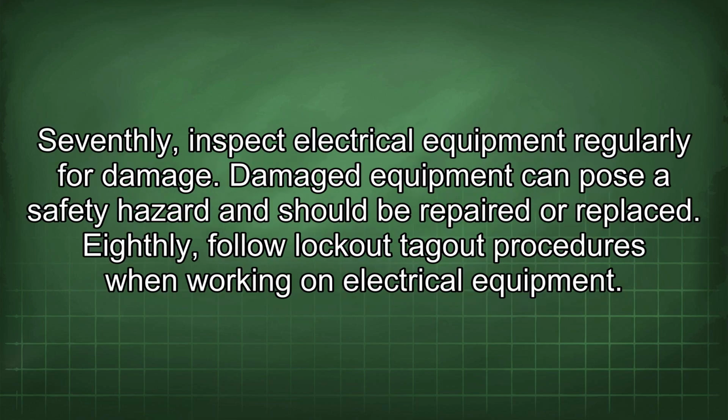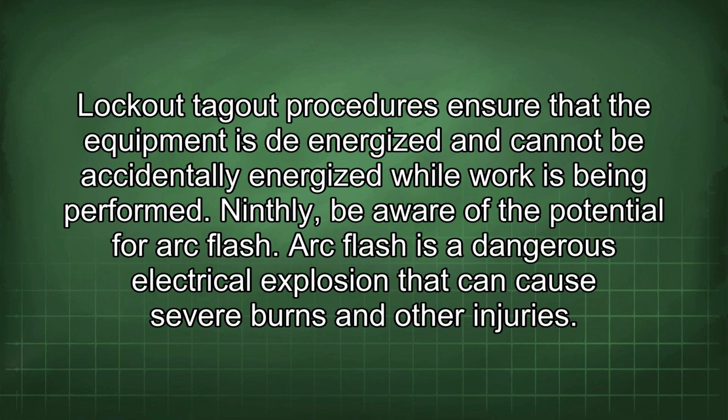Seventhly, inspect electrical equipment regularly for damage. Damaged equipment can pose a safety hazard and should be repaired or replaced. Eighthly, follow lockout-tagout procedures when working on electrical equipment. Lockout-tagout procedures ensure that the equipment is de-energized and cannot be accidentally energized while work is being performed.